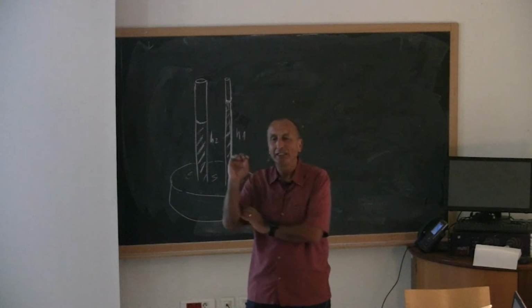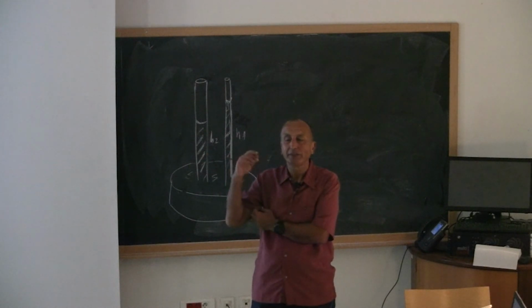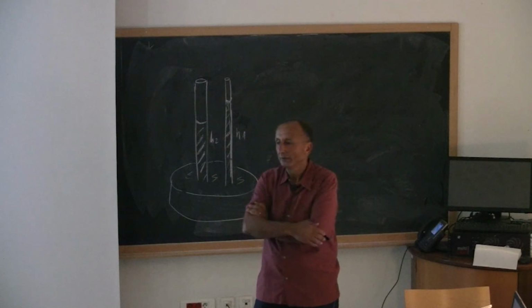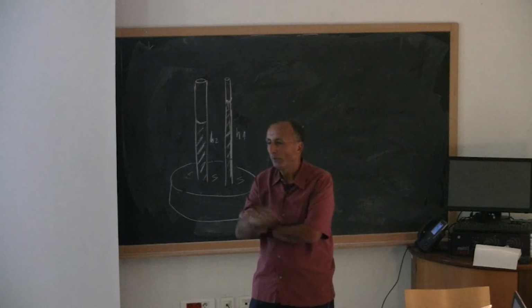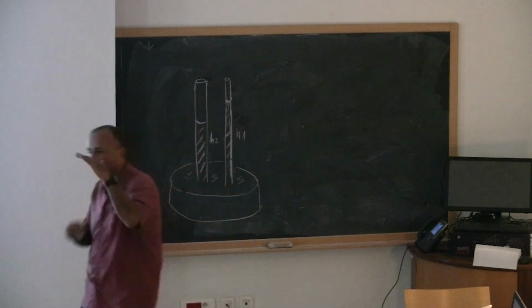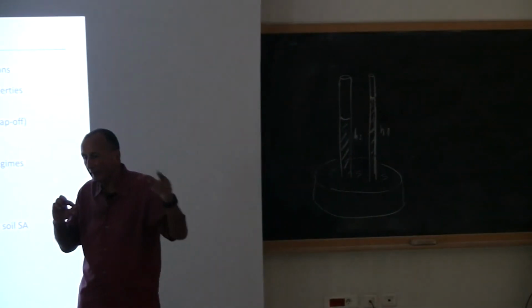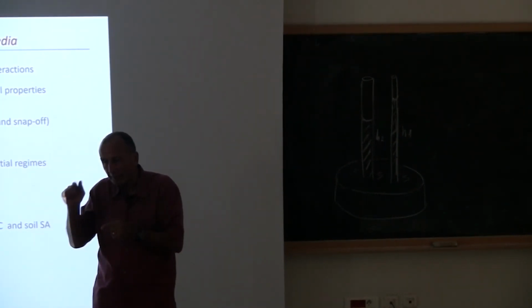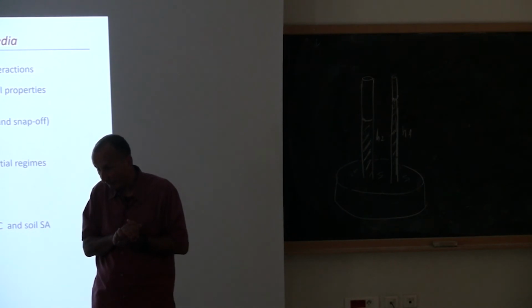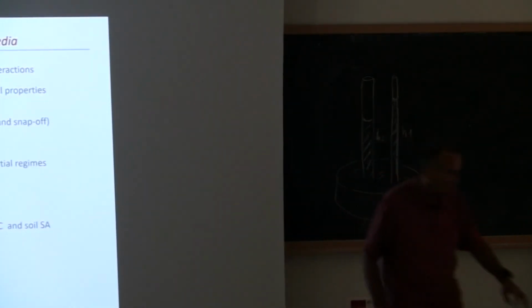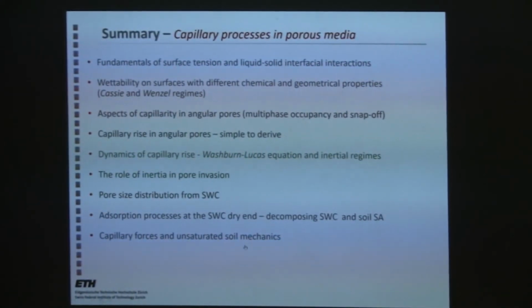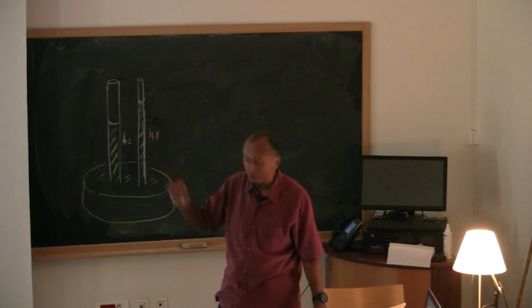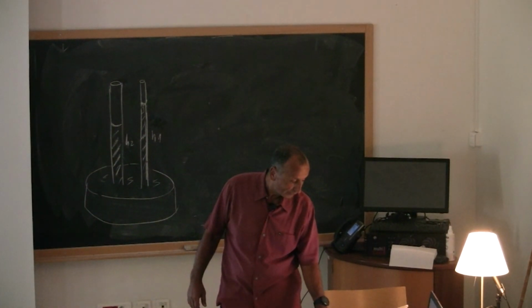But yeah, there are ways to do that with fast cameras, with acoustic measurement, and also with pressure measurement. Nowadays, we can measure. You've shown pressure measurements. What did we see? What you see is fluctuations of the pressure at the bottom of the micromodel that integrates. Yeah, but if I measure at very high frequency, I can measure every jump in the front. Because there was a kind of periodicity in the signal. Yeah, because it is basically coiling and jump, and that's a periodicity. So that's not noise. No, it's not noise. No, we use it.